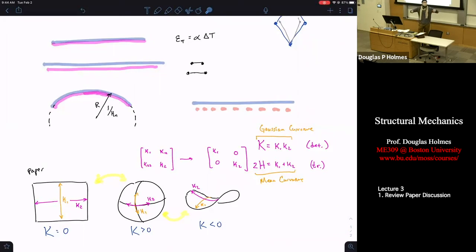You're putting this metal down at an incredibly high temperature, and it starts to warp the structure, just like you're seeing in your baking sheet or the material that I'm passing around. And so a lot of them trying to figure out how to better use metallic 3D printing is trying to figure out, how do we get this residual stress, this stress that's stuck in there because of temperature, away from the part that we're trying to print, and we want it to be flat, or we want it to be this shape.